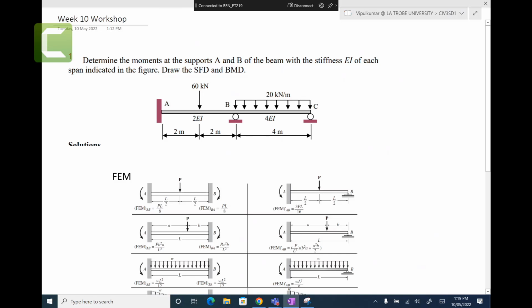Okay, so this is an indeterminate structure. What is the static degree of indeterminacy? Static degree of indeterminacy, force method. How many reaction forces here? 3. How many here? How many here? How many total? 5. How many equilibrium equations? 3. 5 take away 3 equals 2 static indeterminacy, which is used in the force method. Just to give you a review.